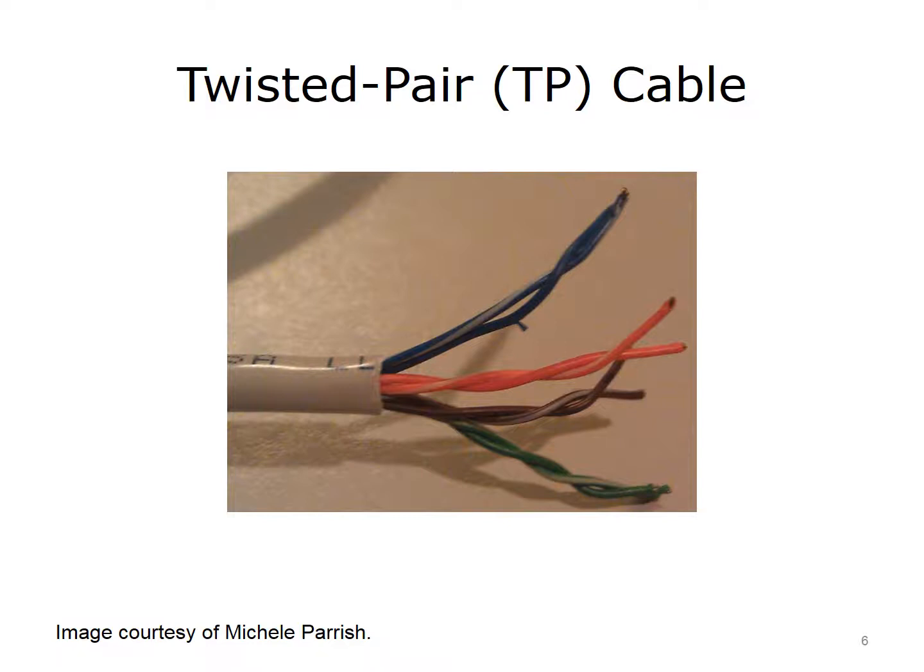A word that you may encounter when dealing with TP is plenum. If TP cable is non-plenum, it will give off a toxic gas when it burns. Plenum cable will not, so it is required if the cable is run in ceilings or air ducts.